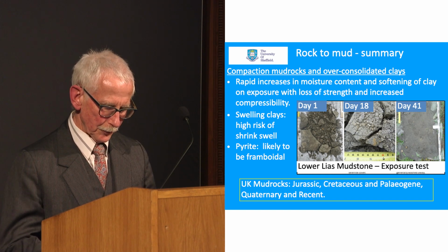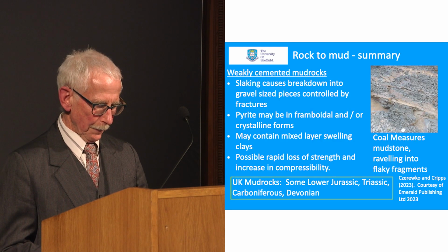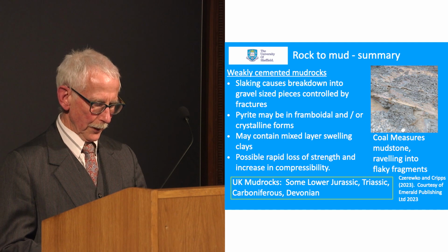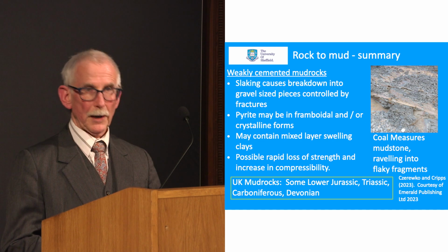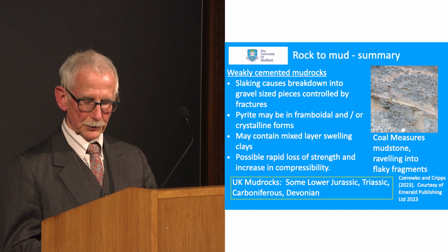Weakly cemented mud rocks are liable to ravel into gravel-sized pieces on exposure. They may contain swelling clays and framboidal pyrite. The changes may be rapid or slower, perhaps months to years, and much faster where there's mechanical disturbance of the material.